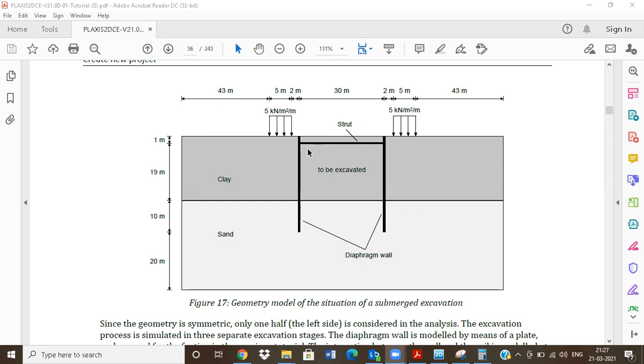You're 100% accurate. If they had mentioned this particular distance, this 30 meters, as a 30 meter diameter, then we could go ahead with a circular footing, axisymmetric. Again, the machinery load cannot be applied for the entire circle. So these are the two constraints not allowing me to choose this as an axisymmetric problem. This problem comes under a plane strain problem in any condition.